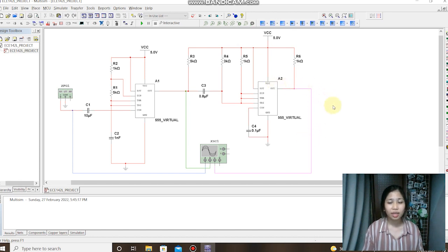In this circuit, a negative pulse applied at pin 2 triggers an internal flip-flop that turns off pin 7's discharge transistor, allowing C1 to charge up through R1. At the same time, the flip-flop brings the output pin 3 level to high.